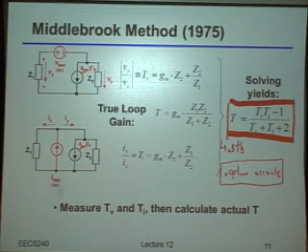I feel like there's something you can crank up. I've seen simulations where you crank up the accuracy and still can't converge, even though maybe physically you should be able to converge. Is there a good way? I mean, the example I saw a lot is when they have that amplifier, like you can crank up that amplifier gain a lot and create problems. Are there good places to check if you're getting that kind of simulation? Like, how can I fix the convergence?